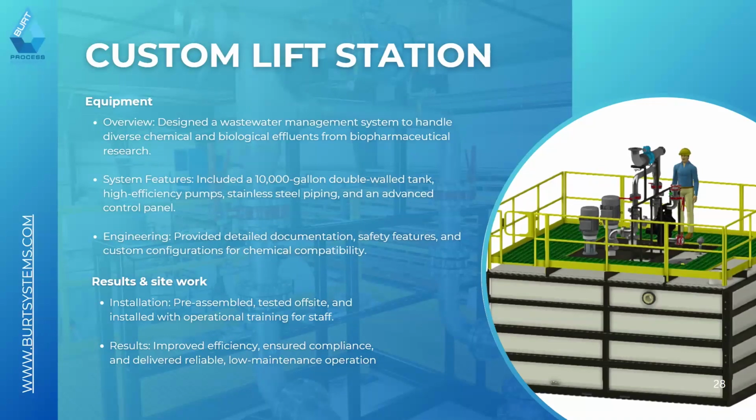To maintain a residency time and treatment. Once you have a pH that's in spec in your lift station, you can then transfer. Once you go out of spec, you flip it back. You still have a reagent injection assembly that goes with it that can be located above the lift station pit. But yes, you can.